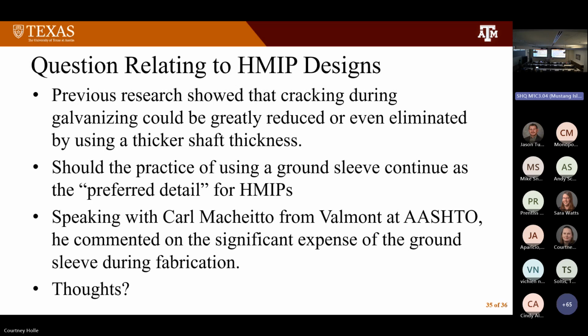Okay. And then just one other thought, like with high mast poles, you say when they dip it in the galvanizing, that's when the cracks form. I'm sure the fabricators know about that now. Are they checking that? My understanding now is most of these fabricators are actually looking right away, where they weren't doing that 15 years ago.